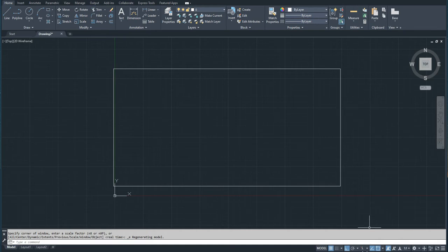I will go to here, guys. Here we have some options. By the way, we have here the grid, the background grid. Here we can display it or hide it. I'm hiding the grid, displaying the grid. And this is snap to that grid. It will restrict the movement to these points only. Keep it, I will talk about it later. Here we have the Ortho mode.